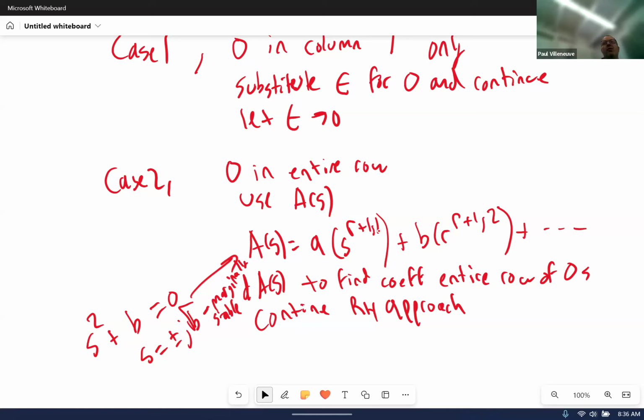Those are the only two tweak cases that you need to do. Most of the time, the reason why we look for a row of zeros is that we just want to know where the j omega axis is. That could also be the bounding for a stable system. If you have to specify a value of k, or a gain, that has a range of k's that result in a stable system, you've got to make sure it stays in the left-hand half plane. So if you find the marginally stable points, then you know it can't exceed that point.